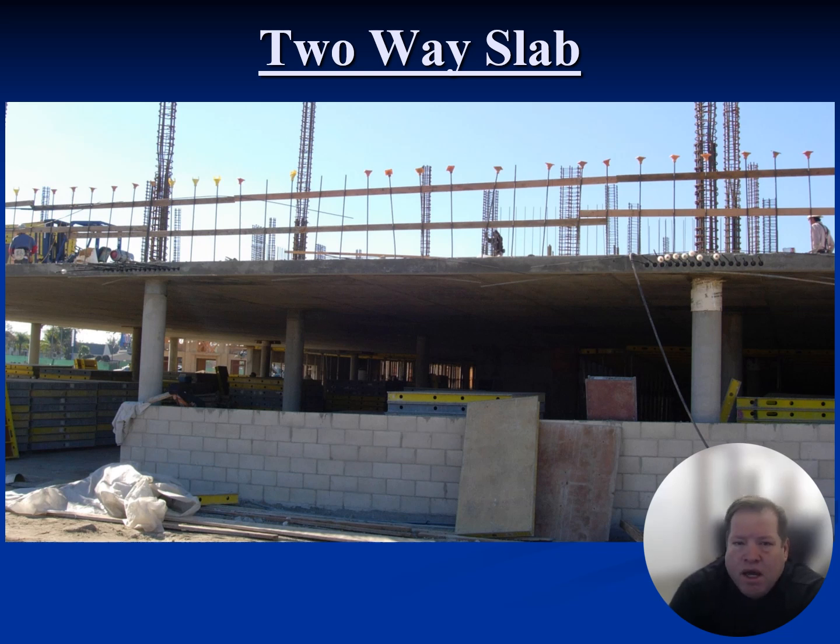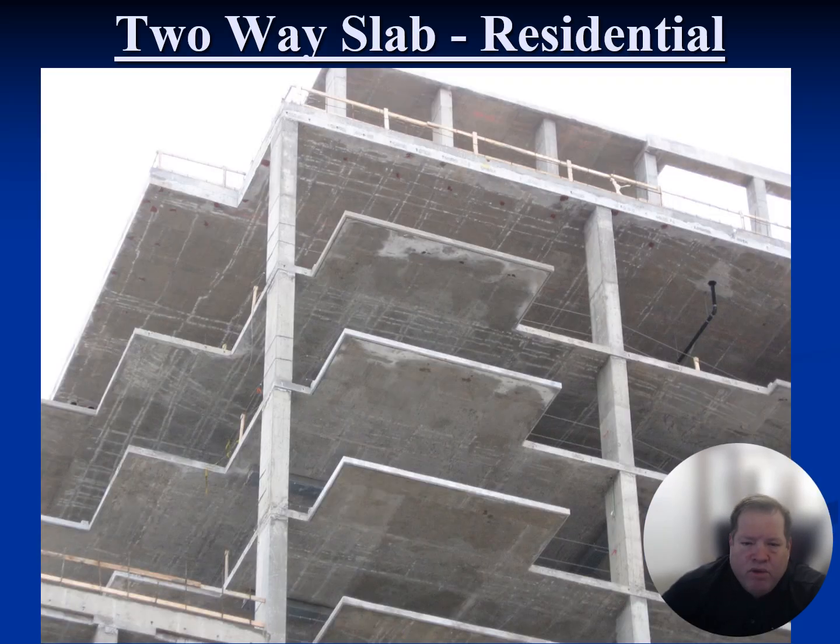Nobody can touch us. One of the things that I've seen engineers get in trouble with, or start getting into very, let's say, interesting designs, is trying to make the slab even thinner than it should be. We win in the size of material. No one can beat us. Don't try to be the extra hero. Do the slab thickness correctly, live with that slab thickness. No one can touch us, but don't try to go down the rabbit hole of taking another 2 inches off, and then you're in the 500 psi compression range, you're 220% over balance and trying to make stresses work. We win the slab, no reason to do anything more than what we're already doing.